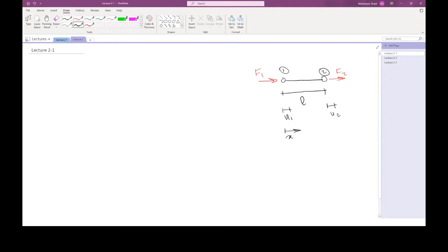Now, we wanted to write everything in terms of the nodal displacement, so everything is linked to the nodal displacement. Now, this is the point of all the work we did last week. So first of all, we wrote the displacement across the elements as an expression. For this nodal displacement, we had 1 minus x over L and x over L multiplied with the displacement at the nodes. Then we had the strain expressed in terms of the displacement at the nodes. So this is minus 1 over L, 1 over L multiplied with U1 and U2.